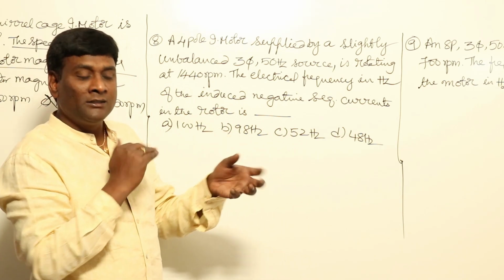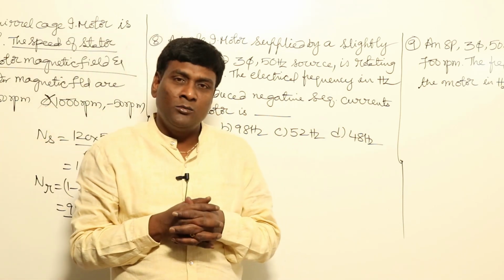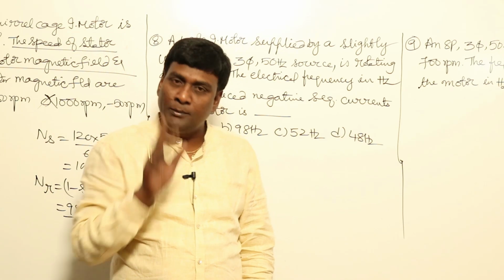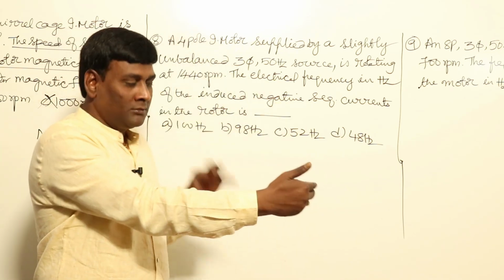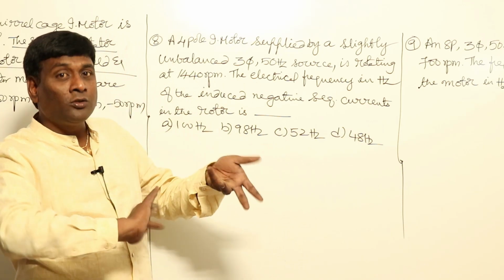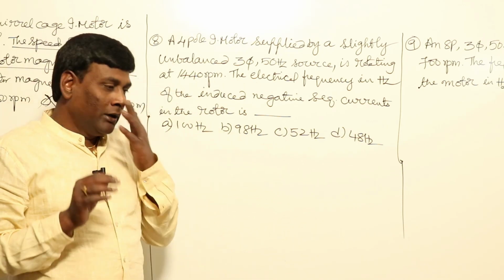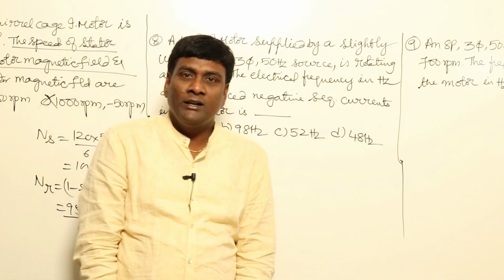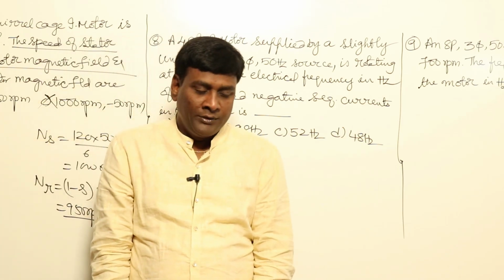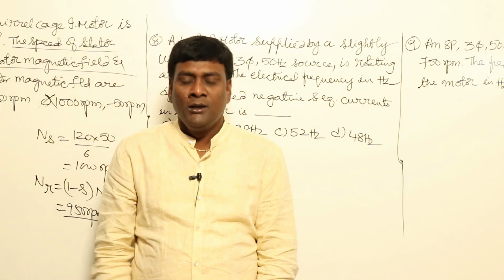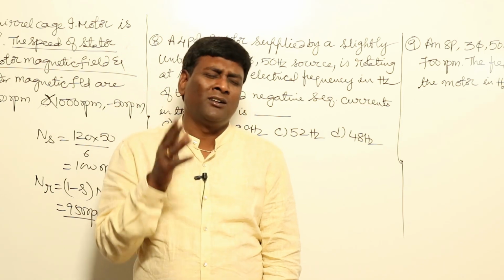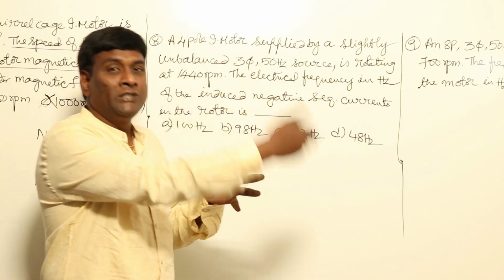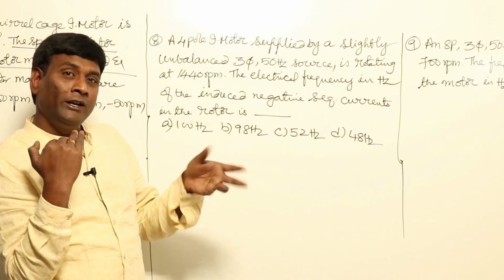The biggest thing in an induction motor is that, independent of the relative velocity between the stator MMF and the rotor, torques will be produced. So for the positive sequence, torques will be produced, and for the negative sequence also torques will be produced. In our harmonics also, one time they asked about slip. A fifth order time harmonic was given, but many faculties felt that it is space harmonic; we will discuss that at a later point of time. Anyway, the rotor rotates in the same direction for both the positive sequence and the negative sequence.